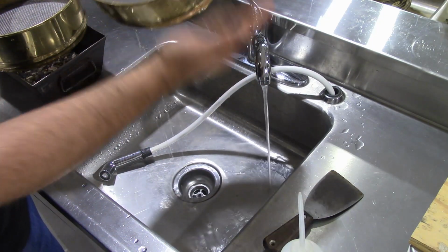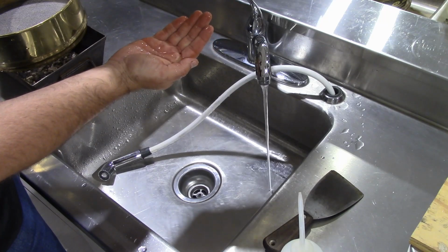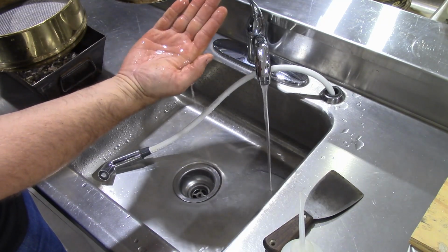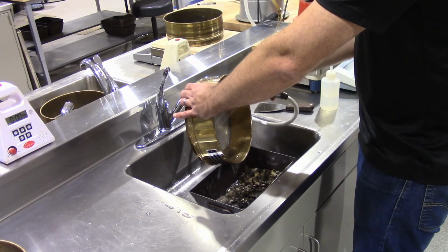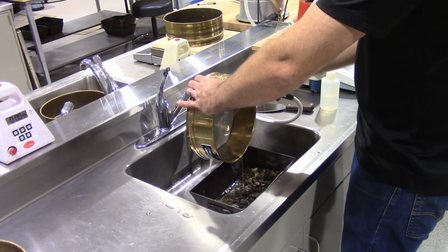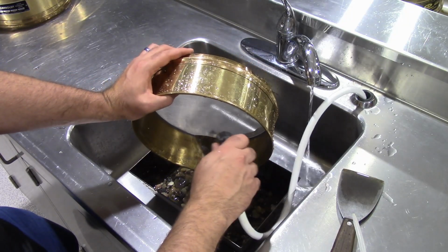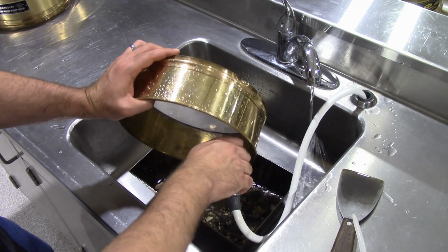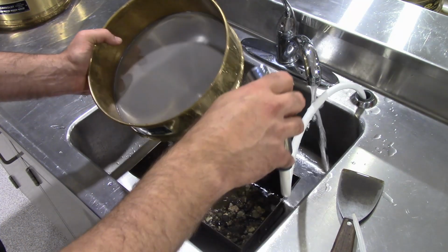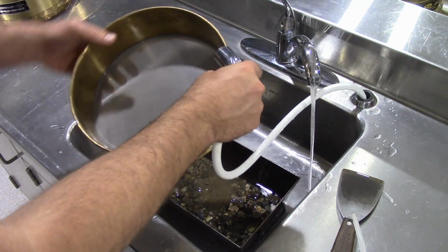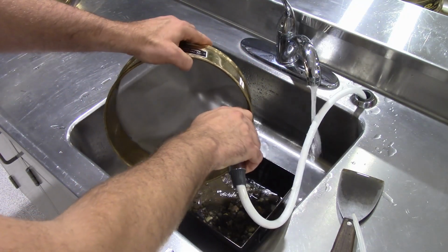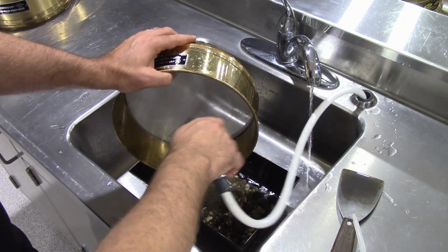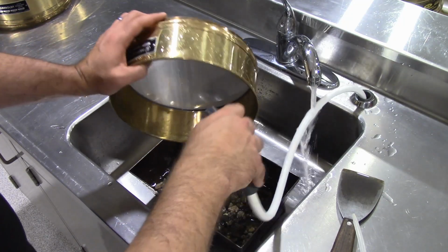Observe the water that passes through the 200 screen. It should be a clear stream of water. If it is brown or gray tinted, that means there is still material passing the 200 screen, and the retained material should be rinsed further. Once the stream of water appears to be clear, transfer all the retained material into the pan. If any material remains on the screen, the loss by wash values will not be accurate.